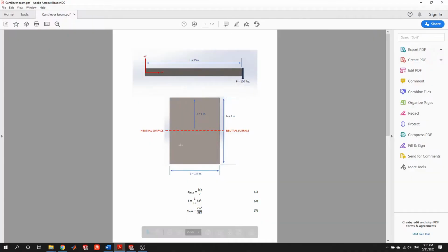And if we look back here at the equation, you can see that as I gets bigger, the maximum stress goes down, and certainly the displacement goes down. Because I is so sensitive to this vertical direction, it's h cubed, orienting the cross section in this direction has a lower maximum stress and a lower displacement. We could load the beam in this other direction where b would actually be the h, but you can see we'll get a higher stress and a higher displacement.